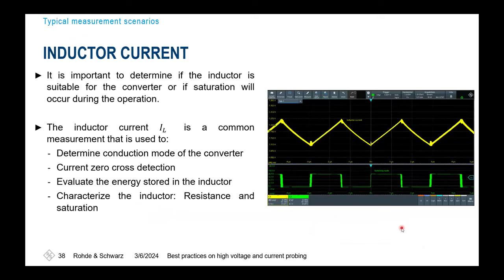In addition, also the inductor current is sometimes quite tough to measure. So to see if your inductor is saturated, desaturated, or maybe also causing you some overvoltages you didn't expect there. The crucial thing here is to measure the inductor current properly, you'll have to change something in your system anyhow. So always be aware if you're measuring something, you might cause issues in your system. Especially if you go to the output of your inductor and you're adding a certain wire, this will change the effective inductance inside your measurement system, and thus you'll see different measurement results at the end.